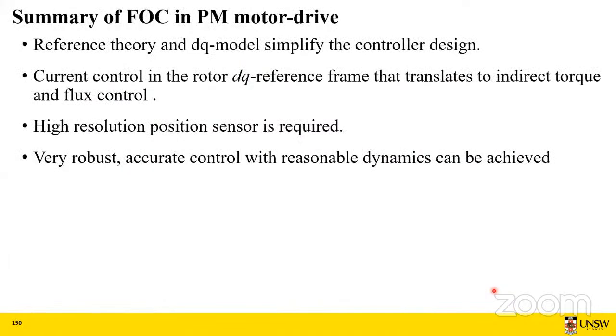So that brings us to the end of this 2 hour lecture of the morning session. In summary, we have looked at the reference frame theory. We have developed the DQ model and understood that by using the DQ model of 3-phase complex machines such as PMSM, controller design can be made simple. And when we use the DQ reference frame, all the quantities become DC quantities. Therefore, the control also becomes like the control of a DC machine.